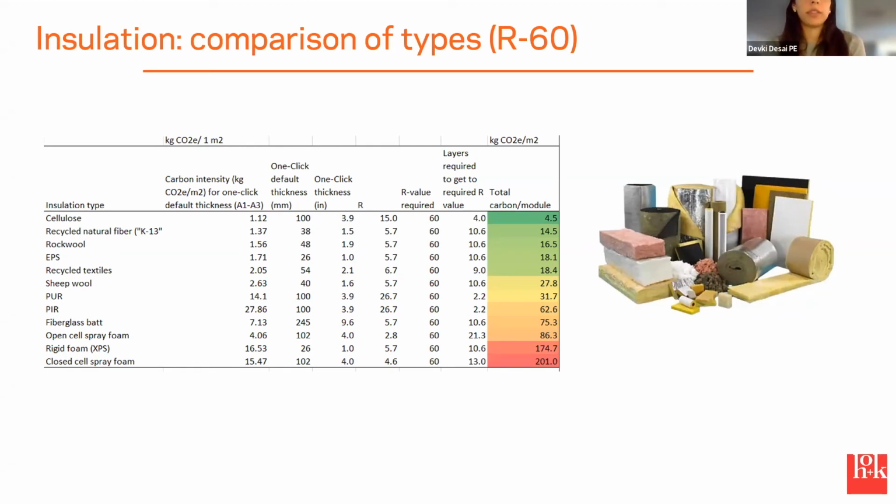A couple of years ago at the Carbon Positive Conference, which is all about buildings going for low embodied and operational carbon, a resounding message in a lot of the presentations was you can't get to the carbon reduction we need to get to and use rigid foam insulation. So that's kind of the first thing that has to go. And it's a little tough because it's such a high performing product in terms of energy efficiency. But then when you look at the embodied emissions that are upstream in order to create that product, suddenly on the embodied side, you're paying a really heavy price for it.